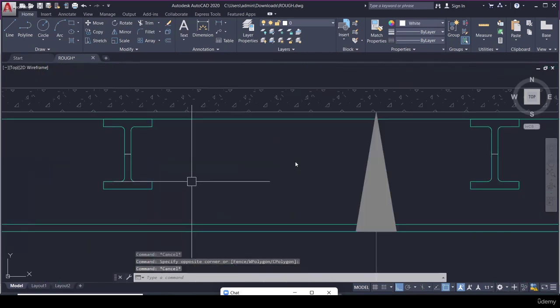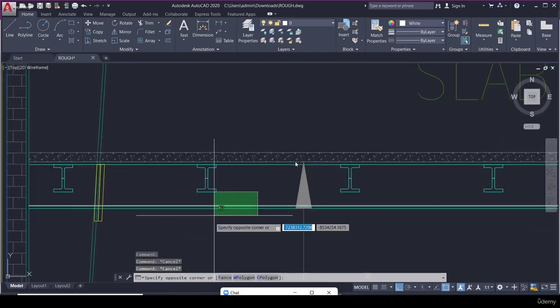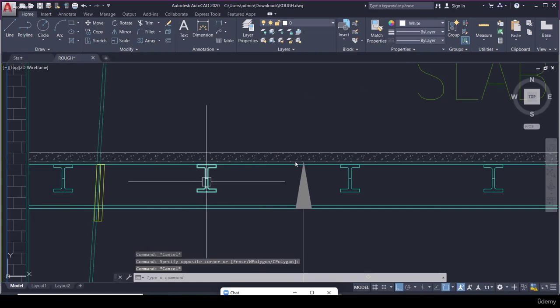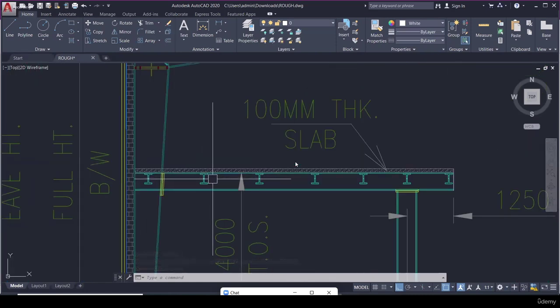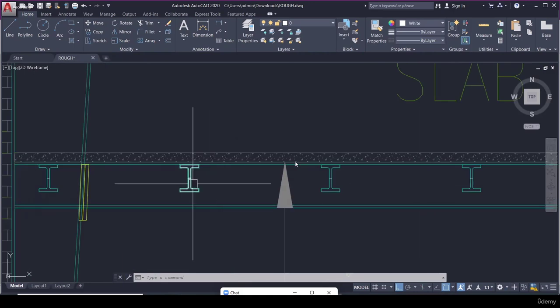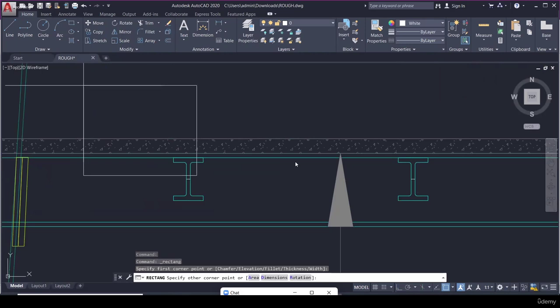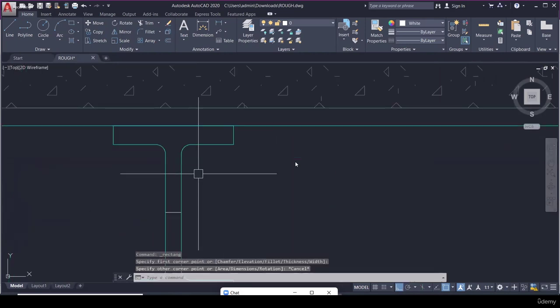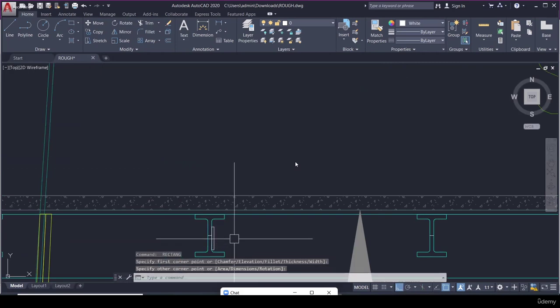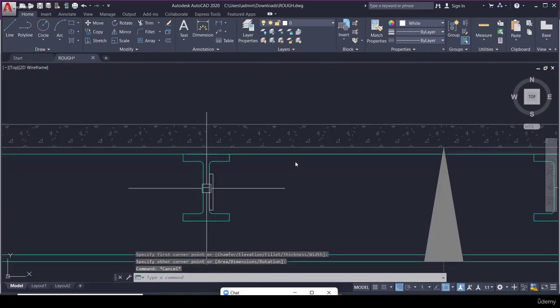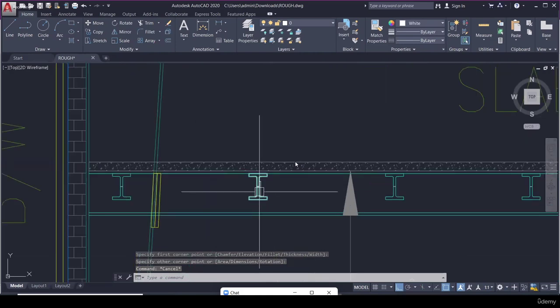These are secondary beams. This is the primary mezzanine beam. This is the secondary beam. So if you observe, this secondary beam will be connected to the web of the primary beam, right? This is the web, the length of the web of the primary beam. So it is connected to the web of the primary beam, by using clips. By using clips, it will be connected to the mezzanine beam.